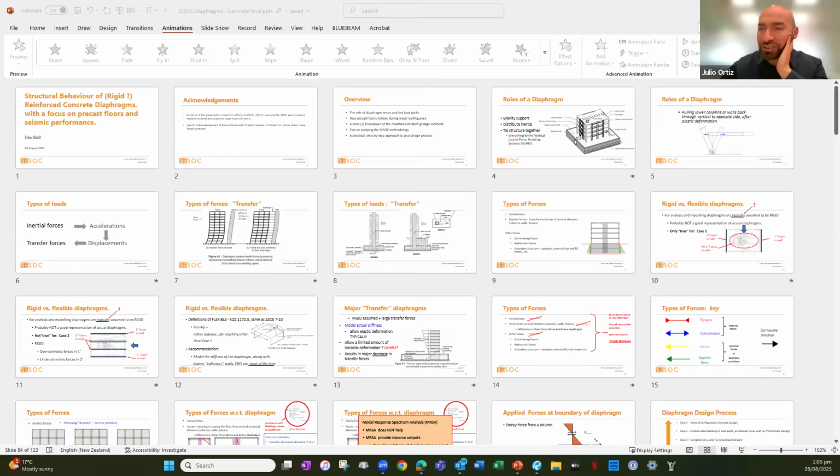Yeah, most precast floor systems with a topping generally end up with cracking over the supports as the topping tries to make adjacent spans continuous. Do we need to account for these tensile forces in addition to the diaphragm inertia forces when analyzing a diaphragm? That's a really good question.